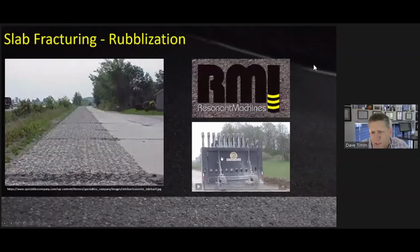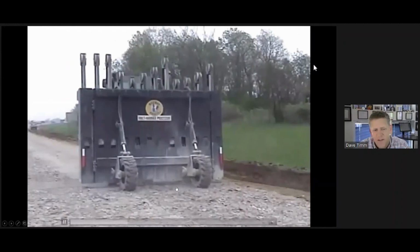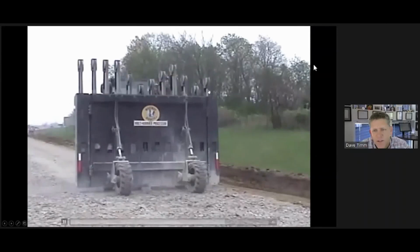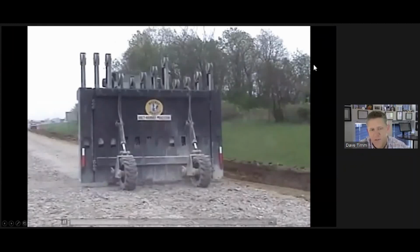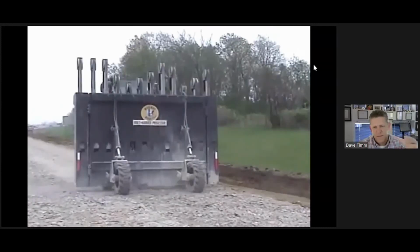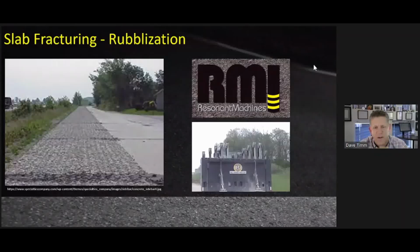The other approach is what's called a multi-head breaker, and this is literally just a hammering machine. There's no sound with this one, but basically you have a lift mechanism. The weight is raised, dropped onto the pavement surface, and it just creeps along, and what's left behind is fractured concrete. I'm not going to get into which ones are more suited for which applications. There's a lot that could be said about when to use various machines and how to tune them, but we're not going to get into any of that. They can be used successfully in a variety of different situations to fracture the slab and remove that slab action.